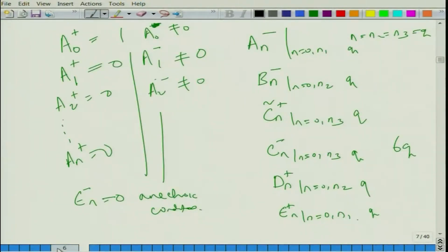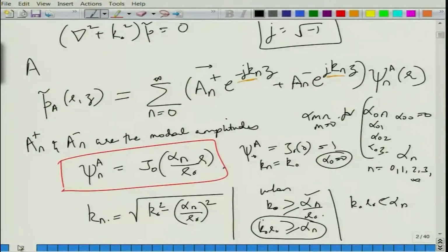We started off with the modal summation formulation in the ducts, and we clearly mentioned that because of the concentric nature of the location of the ports, only the axisymmetric modes will be excited, or those are the ones that are important to be considered. The circumferential modes or the cross modes are not necessary. So, we will consider only the radial modes or the axisymmetric modes, and that is why we have written this formulation. There is no dependence on theta, that is the angular dependence, there is only dependence on radius r.